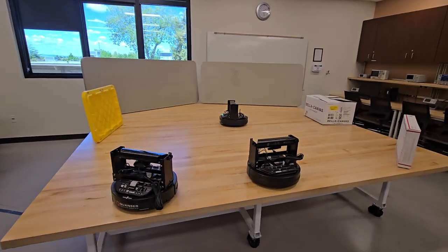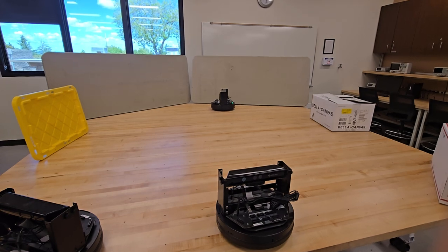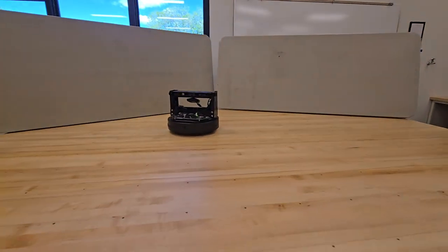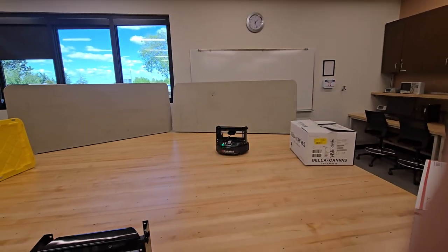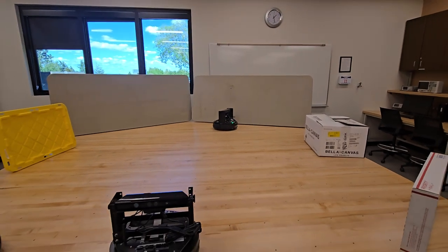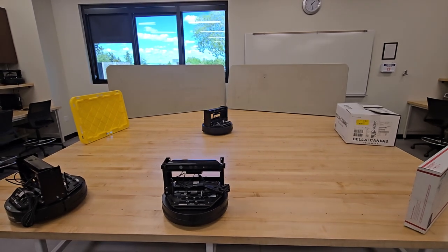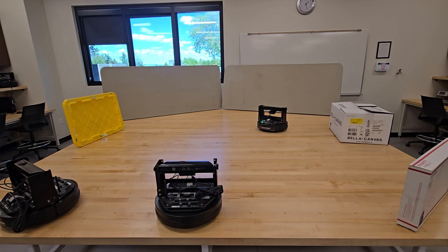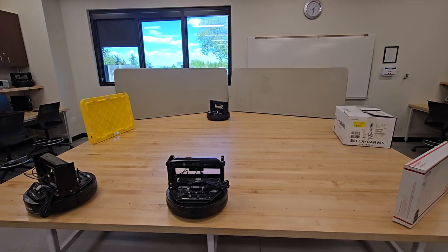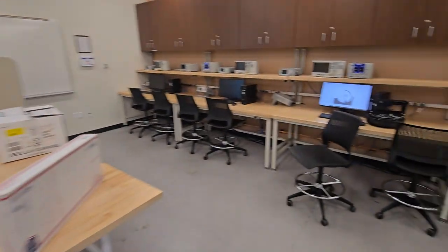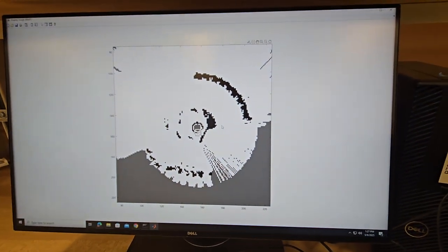The other important thing is, pay attention, this is a 2D map, so it only scans objects that are at the same height as the Kinect. If the object is on the floor or above the height of the Kinect, it is not going to get that. It's just a section of the 3D world. Of course, this sensor can give you a depth image, so if you want, you can convert this to a 3D map. But in this case, my goal was just to show you the 2D section of it. And remember, we can always go back and convert this to an occupancy grid map that is 3D.